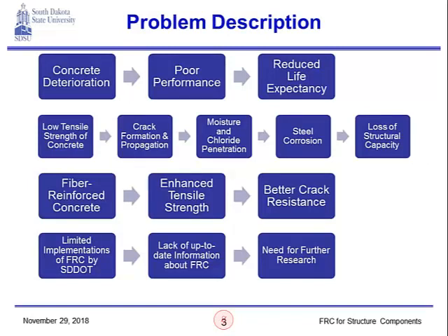So let's start with the problem description. As we all know, concrete deteriorates with time, which results in poor performance and ultimately in reduced life expectancy. And we always aim to increase the life expectancy of concrete, and that's why we introduced fibers into the concrete, creating fiber reinforced concrete, otherwise known as FRC, to help us in mitigating some of the problems that are inherent within conventional concrete. The main reason behind the concrete deterioration is the fact that it has low tensile strength, which basically causes crack formation and propagation with time.